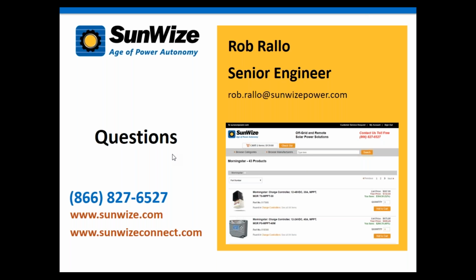Very good question, actually. Let me try to address it in a couple ways. There's nothing you can do to help the cell, because as I showed, if the sunlight on that cell is 0, the entire module goes to 0, or at least that portion of it, because there's a bypass diode that's going to bypass it. What that then means is, if you go to some of our other tech notes with regards to voltage drop issues and temperature correction for voltage drop, basically what ends up happening is that the voltage gets reduced such that no current will flow to the battery.